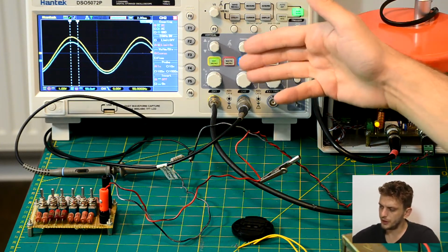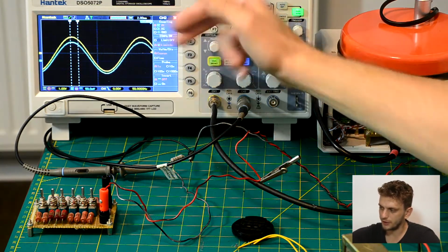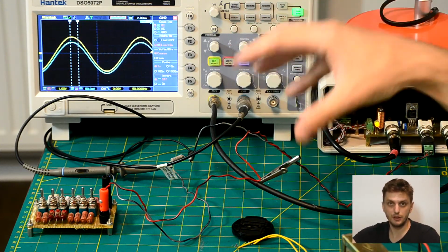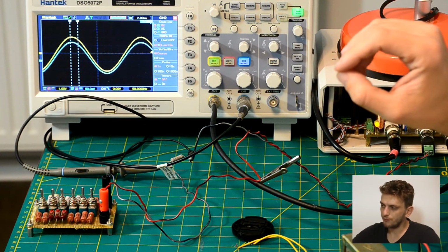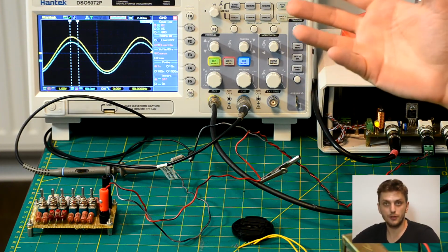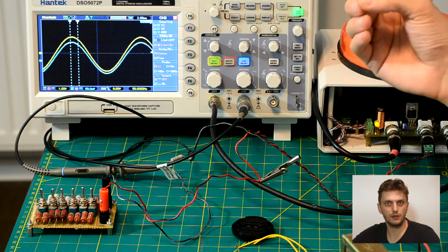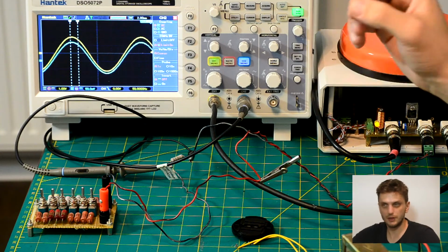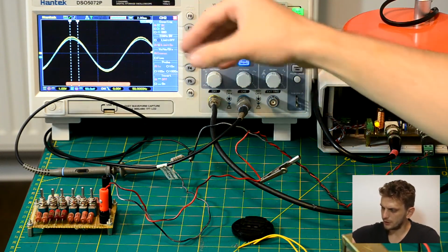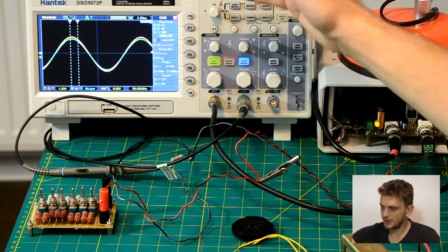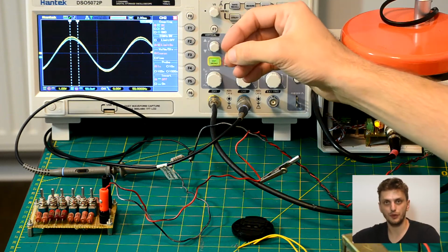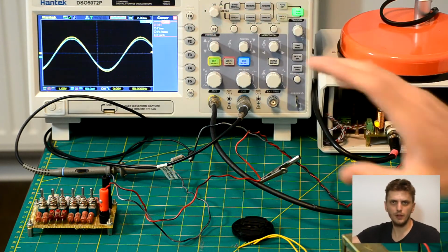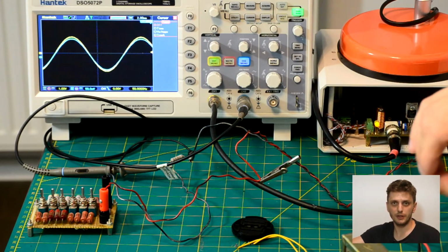I'm measuring the current flowing through the circuit. And what we can notice, looking at the voltage and the current, is that both of them are sine waves, so this is a linear load, but more importantly, as the voltage rises, so does the current. When the voltage drops, so does the current. So we have a perfectly direct link between the voltage and the current in this circuit. If we adjust them a bit, we can see that there's absolutely no phase difference between the two. When we have a peak voltage, we have a peak current. So nothing really interesting is happening until now.